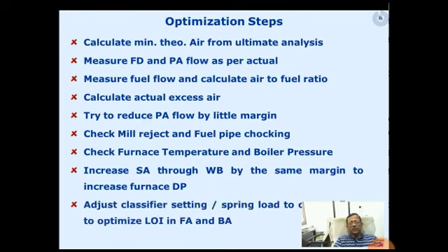So what we do, this is the time when we set the classifier accordingly to change the fines, right? What is the idea? The idea is to have the optimum unburned in the fly ash and the bottom ash, because we are changing the velocity, so we also have to change the fuel particle size. So by adjusting this, we are optimizing the 3T's condition, and this will continue.